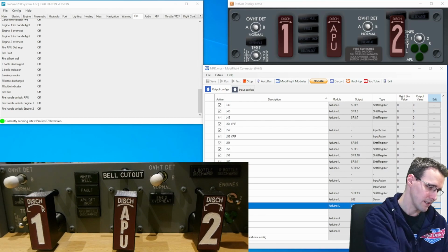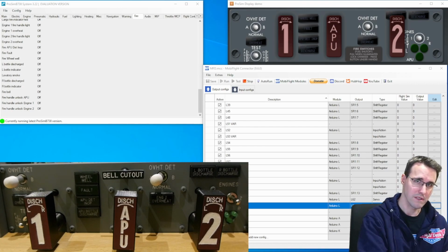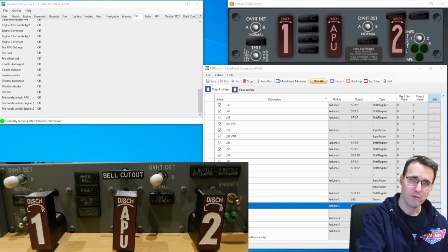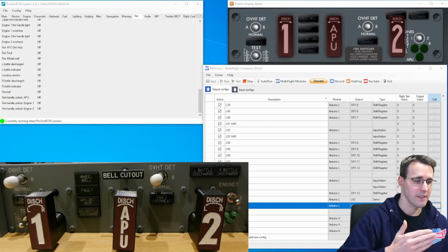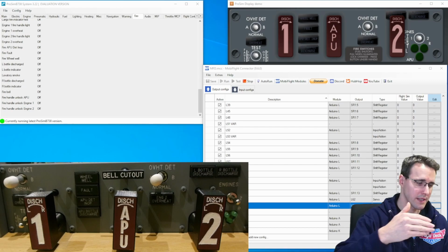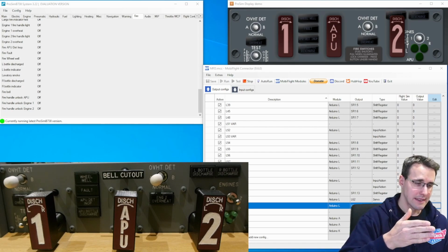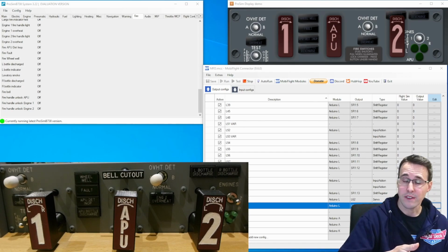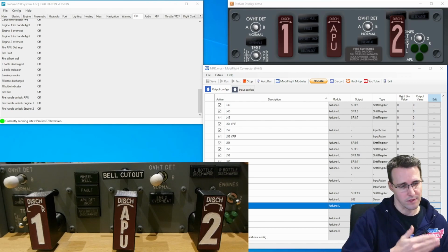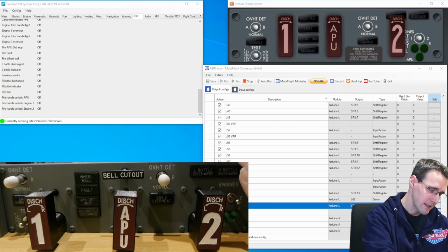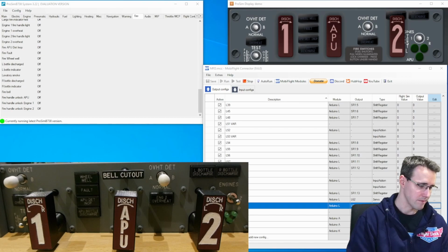there is something not working here. I have to check this later if a configuration or a hardware fault is there. So when you have such errors, check the switch first, if the switch in general is working, and then move your way up. Is the cable connected to the switch right, is it soldered in the plug in the right place, and is it soldered on the right pin on the Arduino, is the pin working, and so on. So I will have to move my way through this failure detection, but I think in this video this would be too much now. So let's jump over this one test and move on.